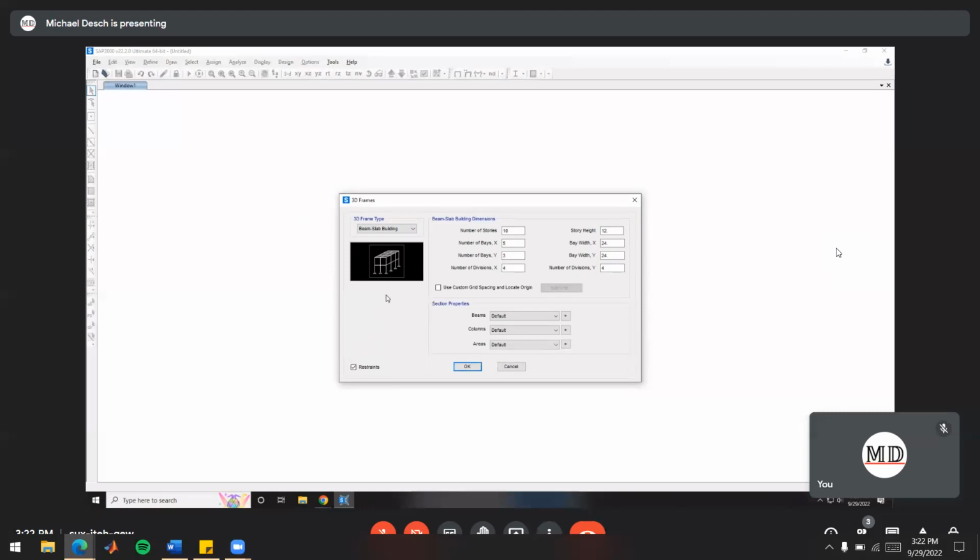We will get to this in a couple of weeks. So this is basically including floors on our frame now as well. If we want to design the floors to be acting as structural elements in conjunction with the structural frame system, we would use something like this. And then finally, we have a flat plate building here, which is just those floor plates and columns, and there's no beams on the floors there.